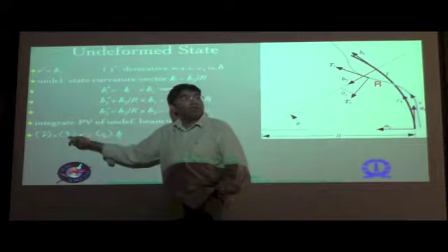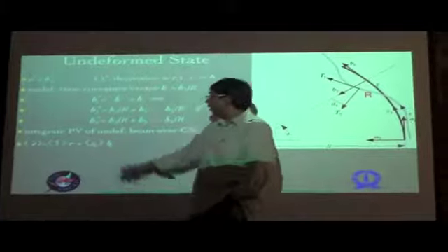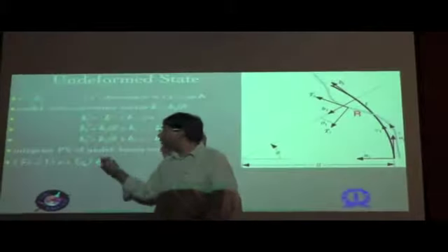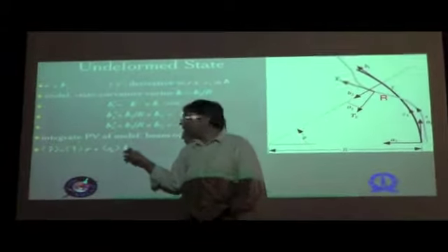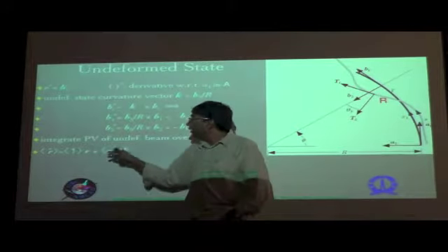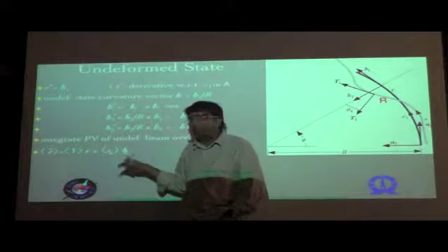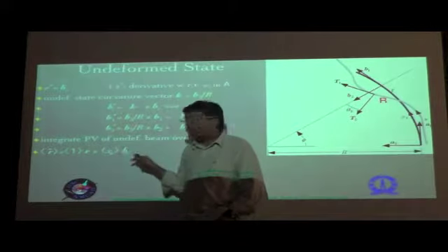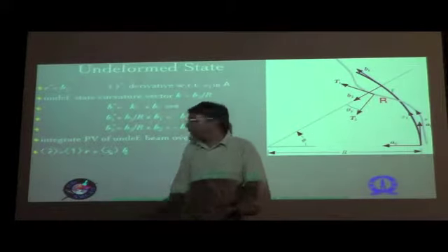using the same symbol that we used in the previous class. And when we come to the second term, which involves x2 b2 and x3 b3, again b2 and b3 are not functions of x2 and x3, therefore the integration over the cross-sectional coordinates x2 and x3 is only over x alpha. B alpha is taken out of that, right?